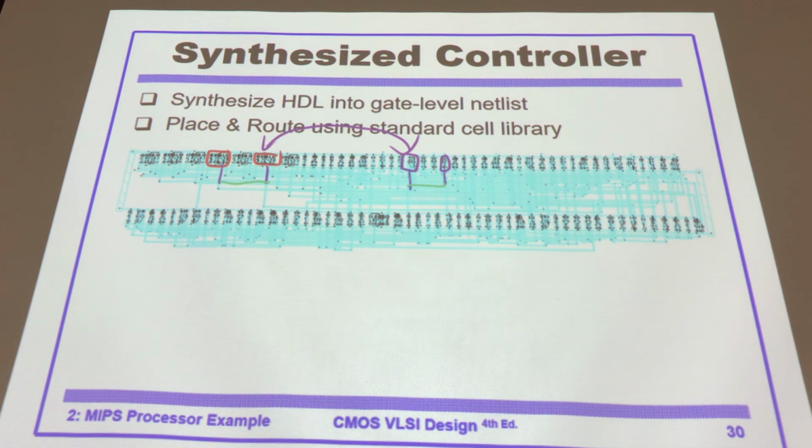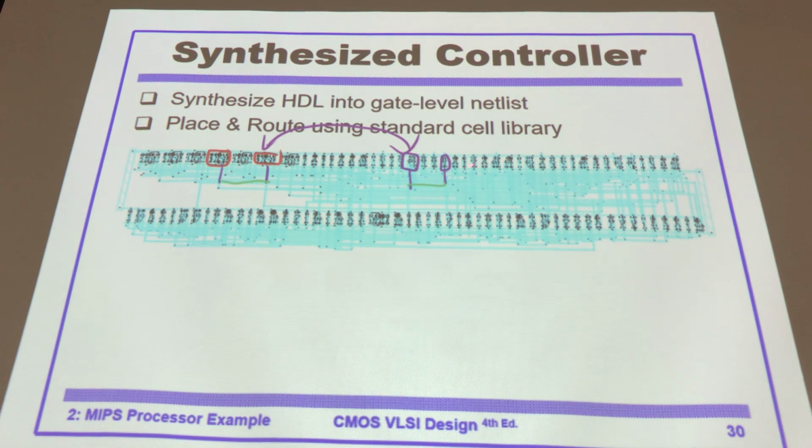What's the benefit by doing that? By doing that, this horizontal line could be the same line, the same track. You don't need two different tracks to connect these four cells. And then your channel, the routing channel, can be narrow, saving some chip area. Let me repeat it.